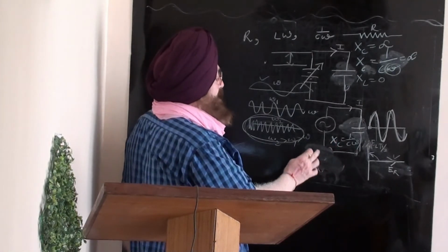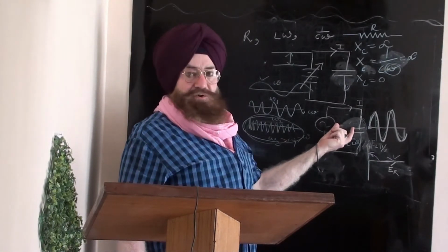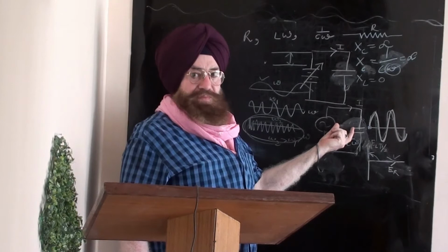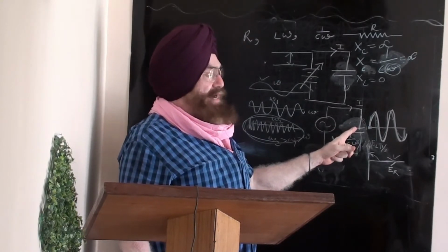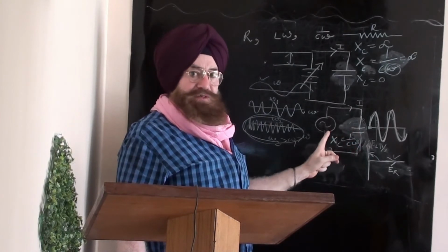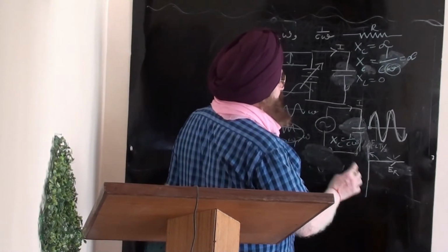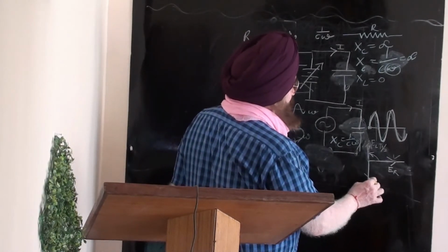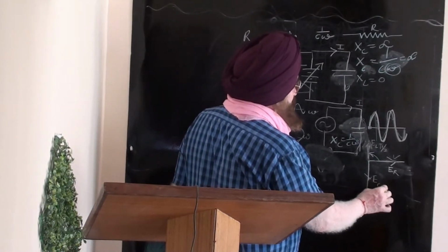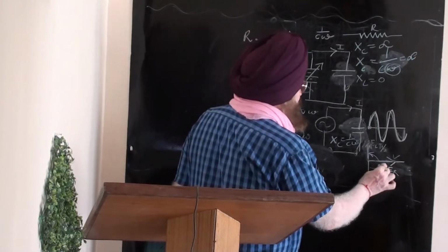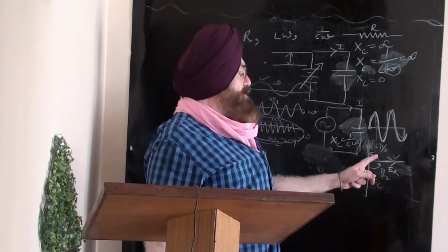And again, in the same way, the voltage and current will not dance together here also. Again the current becomes 90 degrees out of phase to the voltage, with one difference: now the capacitor voltage is along this side. This is the voltage across the capacitor. It again differs by 90 degrees to the voltage.